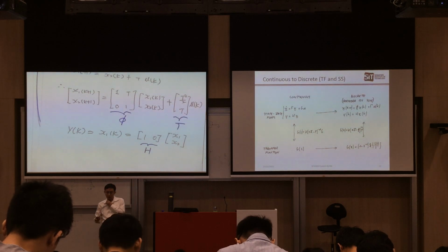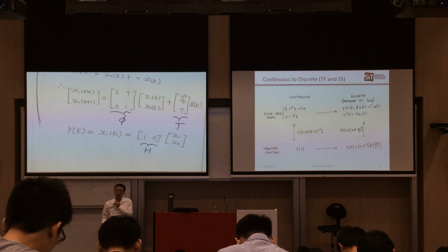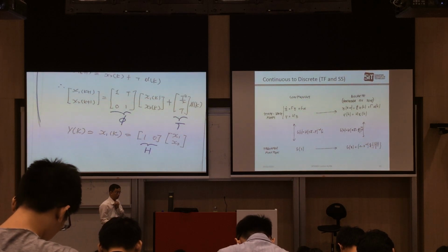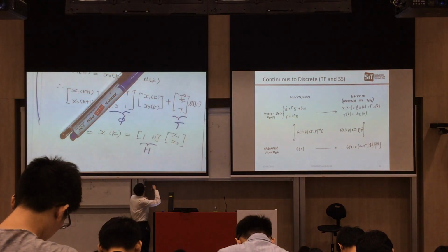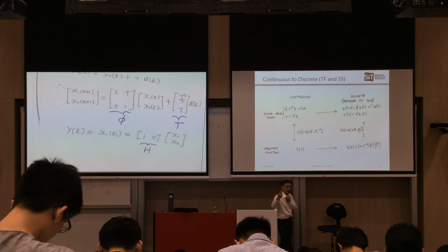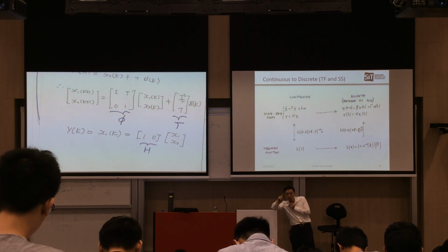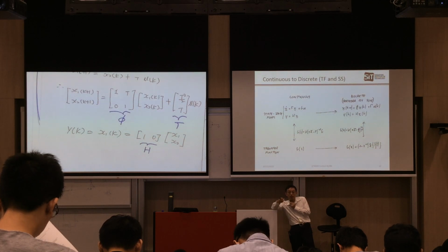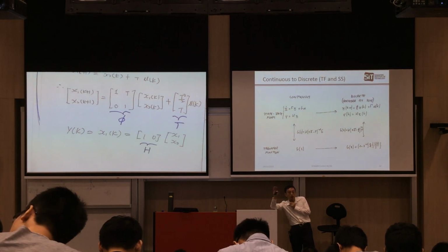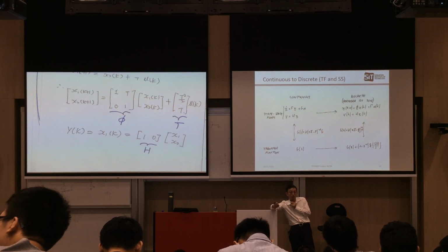The good thing about the state space form is that it is always only first order. They are always first order differential equations. But where does the order go? In my example, the GS just now is second order. If it's second order and you convert to state space, your state space is first order. Then where does the remaining S go? Basically, your second order becomes a second order vector. Your order of differentiation converts to the order of the vectors, and to the order of the matrices.